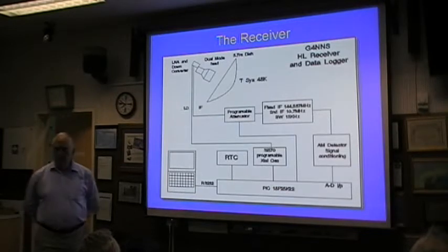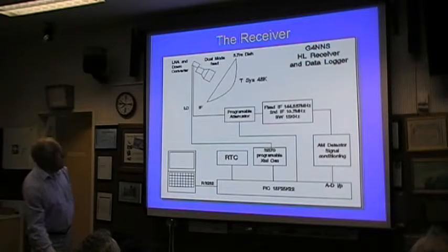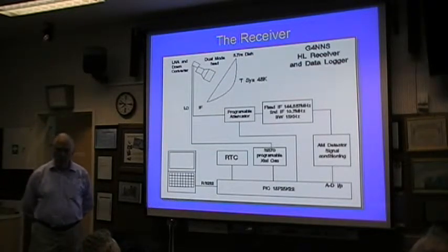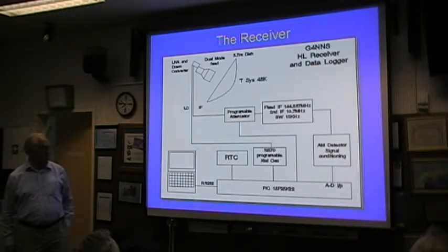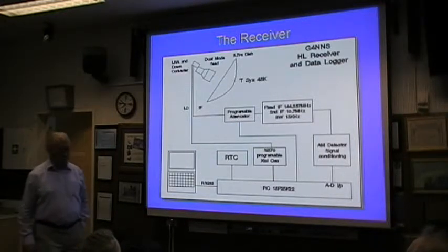Now a bit of radio. So we have a dish, we have a feed. We're trying all the time to keep the T-sys down as low as we can, and luckily with the advent of high electron mobility transistors developed for the satellite TV industry, we can achieve quite incredible results. The system, my system, the T-sys is about 48 Kelvin. No refrigeration required to do that. So it's pretty sensitive.